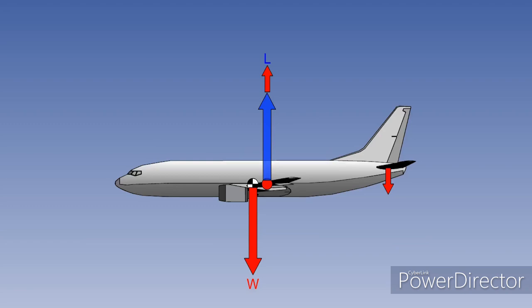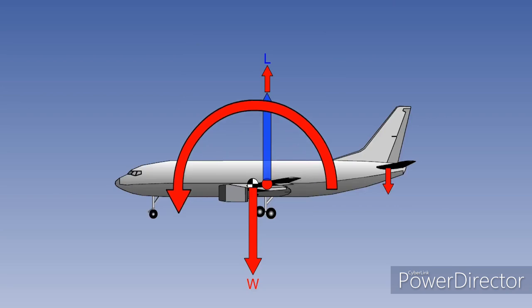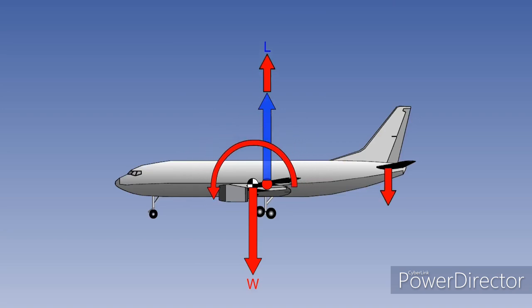With landing gear up, the thrust-drag couple is not great, but when the gear is lowered, the profile drag below the CG is increased, which gives a nose-down pitching moment. This must be balanced by increasing the downforce of the tailplane, which in turn needs more lift to balance it.